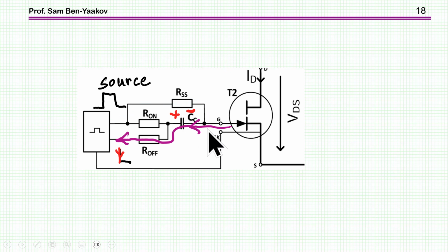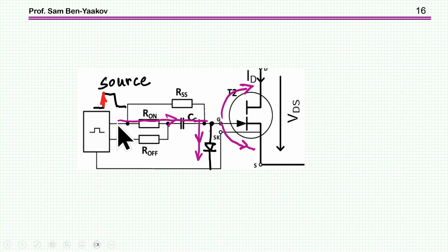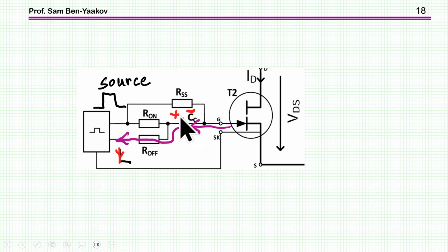And then we have this transition back. When this transistor is on, this of course will be off. And then you see this capacitor is now already charged due to the current that was passing this way. So it is charged here. And therefore, during this time, we actually have a negative voltage imposed on the gate, added, of course, to the voltages according to this network.